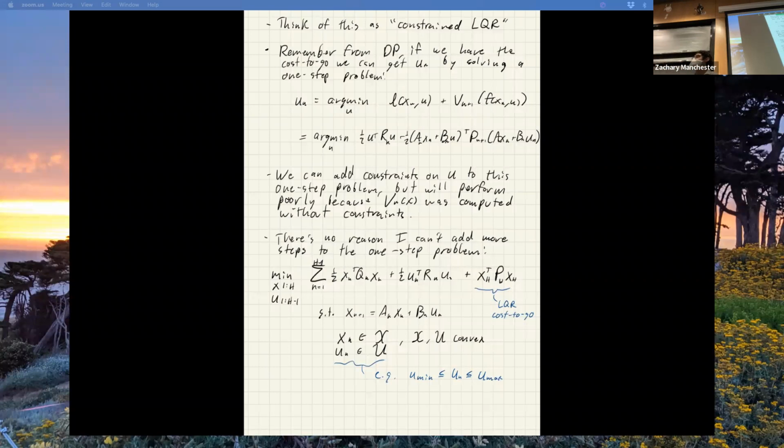Those are physics. Yeah, but as long as you stay within those bounds, you can change the constraints to an inner set. Why would I do that? To make it converge faster. So basically, my motor can produce something like 10 Newton meters of torque, right? In general, I want to use all that torque to make my robot do cool things.